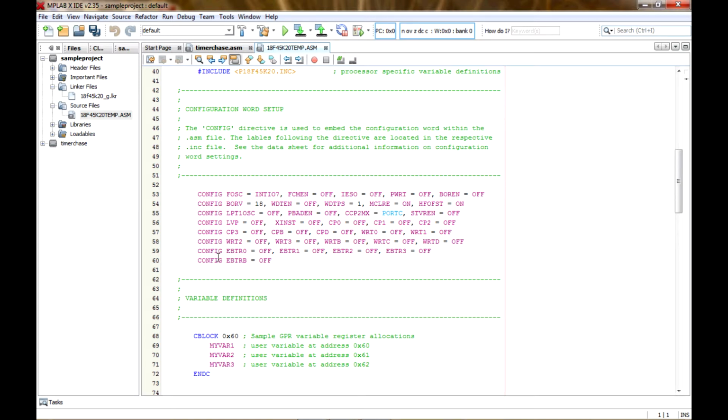You will have to read up in your data sheet about this, but I've found even through the data sheet it can be hard to find certain things, like how to turn a watchdog timer on and off. Some PICs use just WDT, and some use WDTEN for watchdog timer enable. But it is all in the data sheet if you search enough.